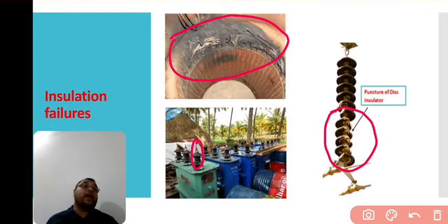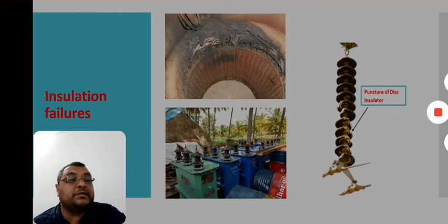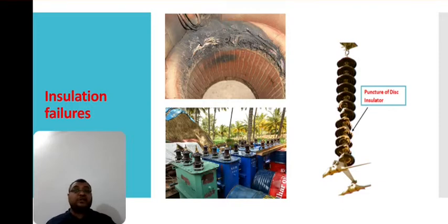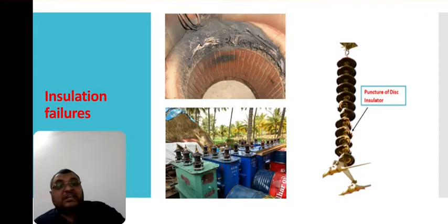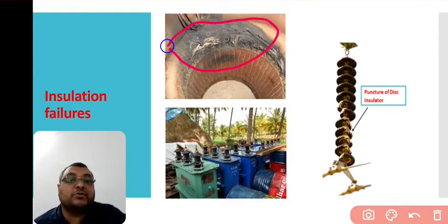in the power system. And how this damage occurs: it occurs mainly due to the dv/dt stresses. You can imagine this. When you consider the failure of insulations, premature insulation failure occurs due to partial discharge as a result of peak voltage, which is the dv/dt and high frequency I discussed. And if the high dv/dt creates a non-uniform distribution of voltage across the winding, then such a failure will occur.